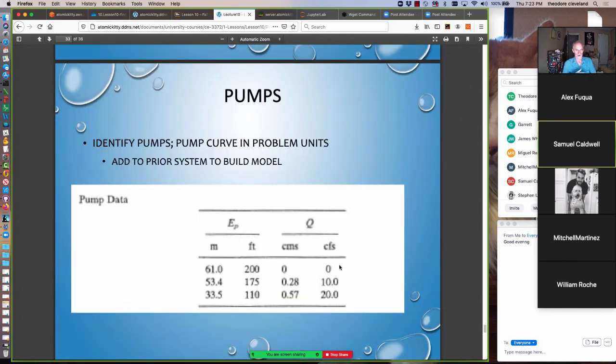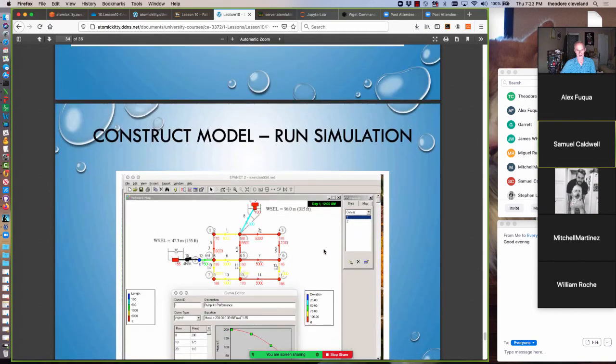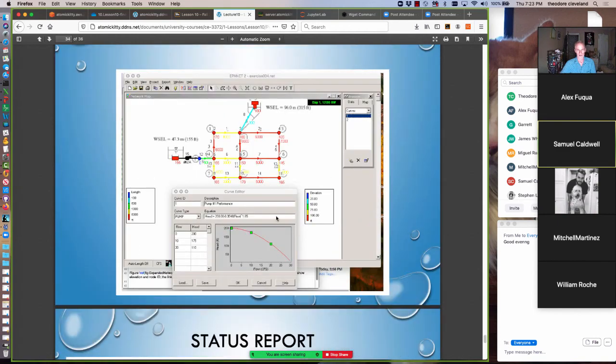Or we can change the pump curve, which involves only 3 unit conversions from cubic feet per second to gallons per minute. So only an idiot would change the node values, so that's what I did the first time I ever did it. But instead, change the pump curve. So we would build that prior to actually constructing the model. And here's the model, and we're going to go look at it in the actual software.